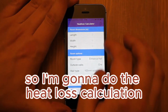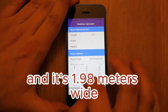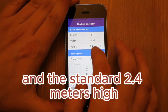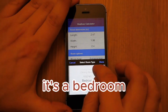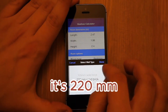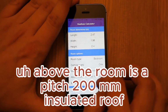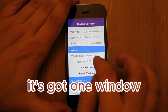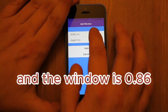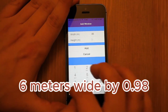So I'm going to do the heat loss calculation for bedroom 3. So it's 2.47 meters long and 1.98 meters wide and a standard 2.4 meters high. It's a bedroom. It's got one outside wall, so I'll leave that outside wall. It's 220mm solid brick. Above the room is a pitched 100mm insulated roof, and below the room is a heated room. It's got one window which is a plastic double glazing, and the window is 0.86 meters wide by 0.98 meters high.